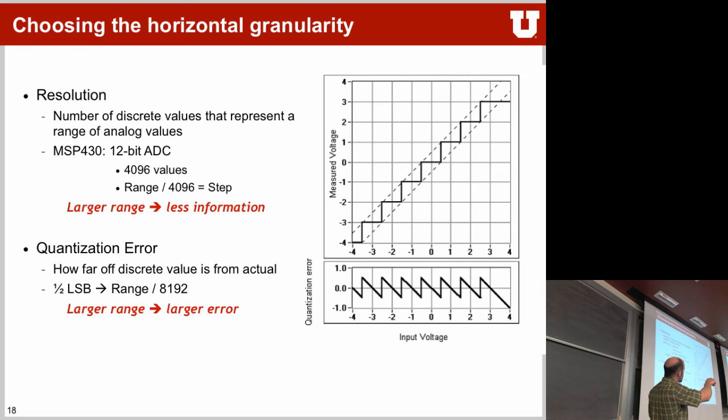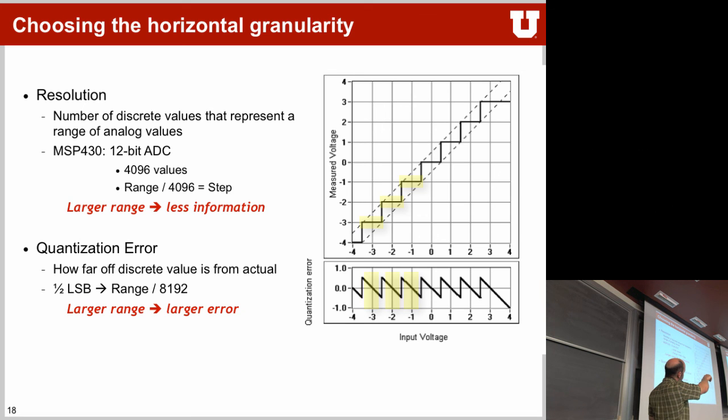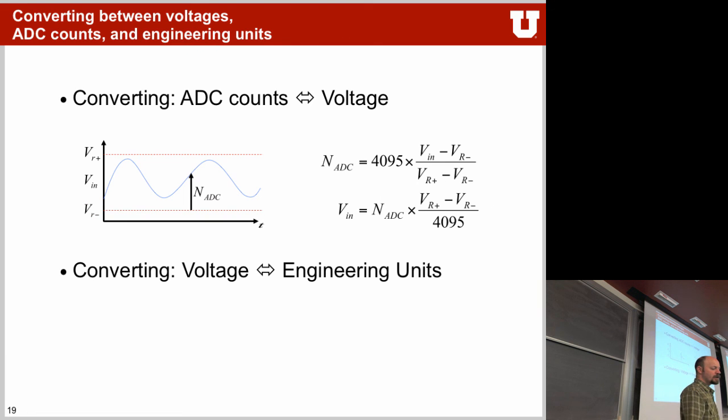So what happens is in between here, the transition maybe happens in between half the voltage. So we will have -4 over here. Then the actual voltage is now becoming -3.6. So we make a minus error in our actual quantization. And then it jumps up to -3, but we are actually not at -3 yet. So we are too high in our voltage before it goes down, down, down. Here we hit the perfect spot where we don't have an error, etc., etc. So that's what the quantization error is with respect to a real signal.